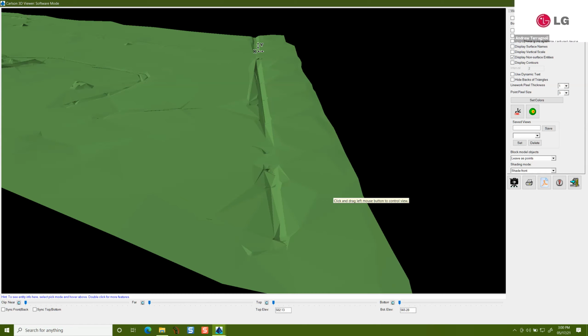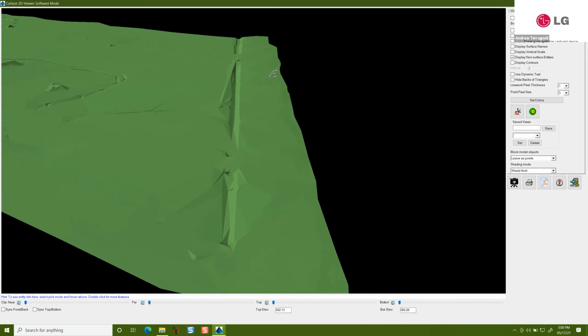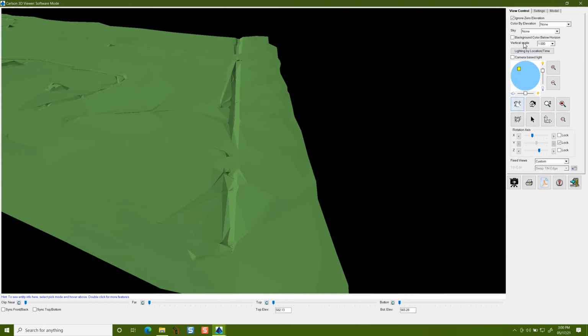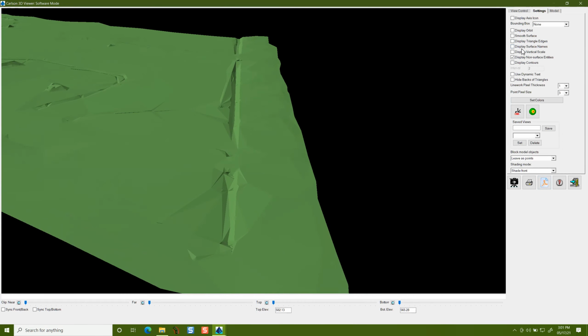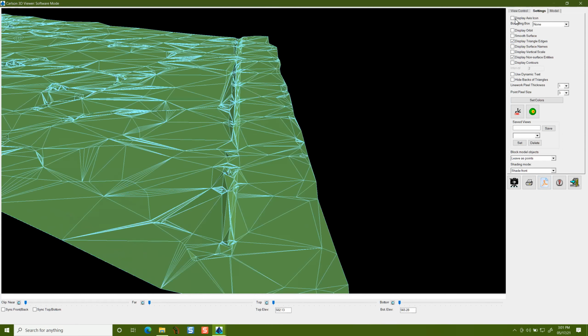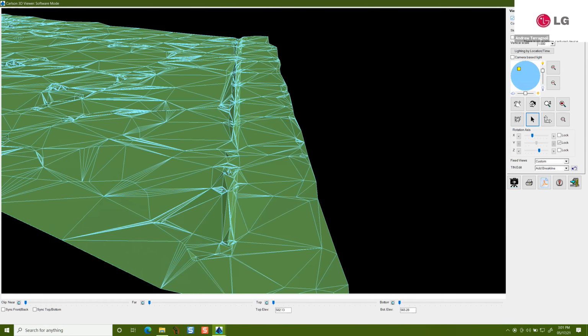That's a break line because right now you can see that the break lines go right through the center line of road. In fact, let's turn this back. I'm looking at the surface. Let's see if it will let me. We can see the results of it in just a second. Just primary edges. You can see it's just cutting right through. They had no center line of road break line at all.